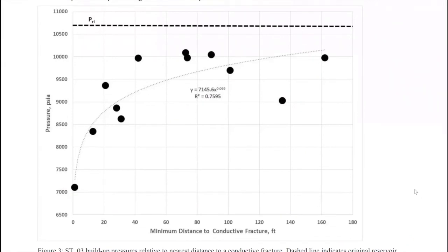And it was linear flow, I don't remember the number, but let's say on the order of 100 nanodarcies, which is kind of what we think the permeability is. So what that data showed, and it was a direct observation you could look at, is that there wasn't an SRV. There were propped hydraulic fractures, and then there was fluid just flowing through the rock towards the fractures.